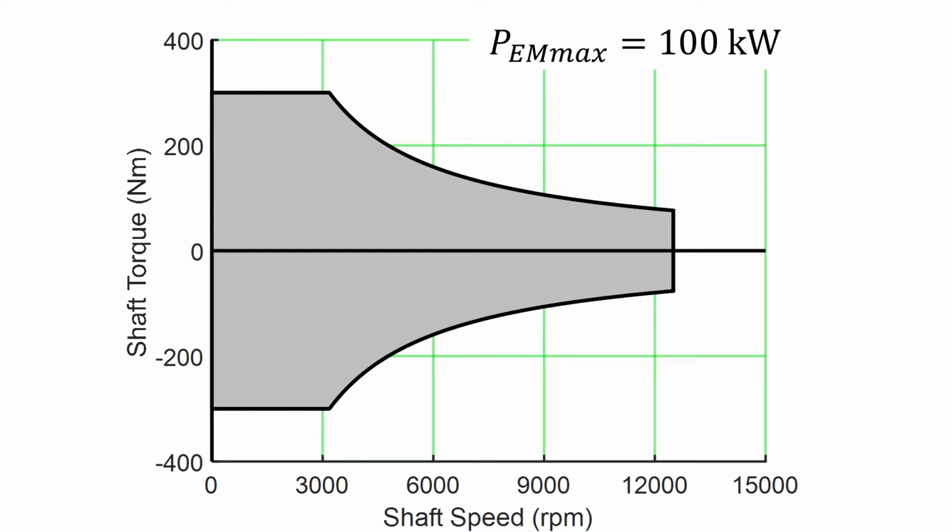Notice that the base speed is reduced when the maximum power is reduced. Here the base speed is down to about 3000 RPM. To design machines which have a wide field weakening region can be problematic though. Often this approach leads to a mechanical power output which isn't constant in the field weakening region. So often the base speed is not lower than about 1/4 of the maximum speed. Should the ratio between base speed and maximum speed be lower than that, it is likely that it would be better to use an additional gear rather than to reduce the base speed of the machine further.